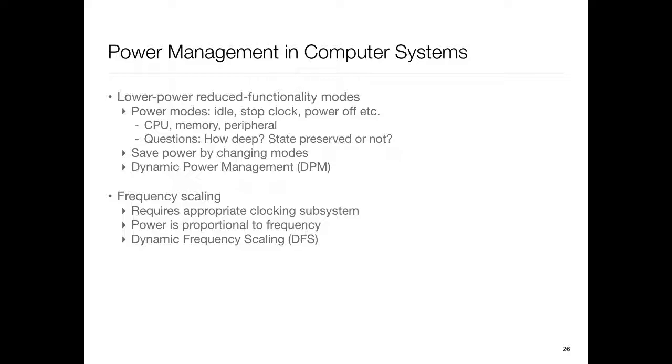Now there are second order effects here, because when you change the frequency of the processor, the rest of the system is still operating at the same speed. Your bottlenecks may reside somewhere else. So if you increase the frequency from 10 megahertz to 100 megahertz, it doesn't necessarily mean that your system will do 10x better, because some other interface may become the bottleneck, and therefore your speed gains begin to peter off. So there are second order effects that you have to be aware of.